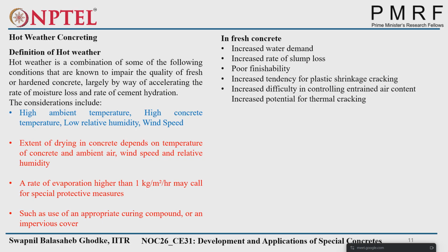So how does it affect fresh concrete? What happens is, as the temperature increases, hydration increases. As hydration increases, to get the same slump, we have to increase the water demand, right?